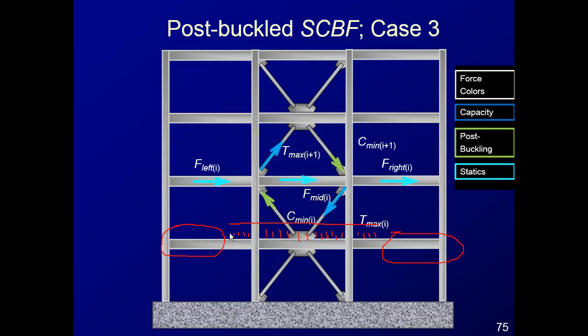And so instead of having a beam that is the full rectangle of your floor plate, if you're only using the shear here and the shear here, maybe your beam looks a little bit like, I don't know what that is, a sort of truncated football. And that could affect the magnitude of your chord forces, or it could just be a question of what your load path is.